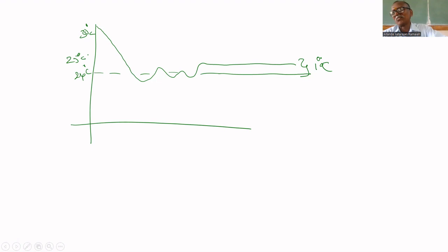Now the error is 0. Always the additional input depends upon error only, not speed. The difference between set point and PV only. The additional input is proportional to what? Old error. It is proportional to the old error.